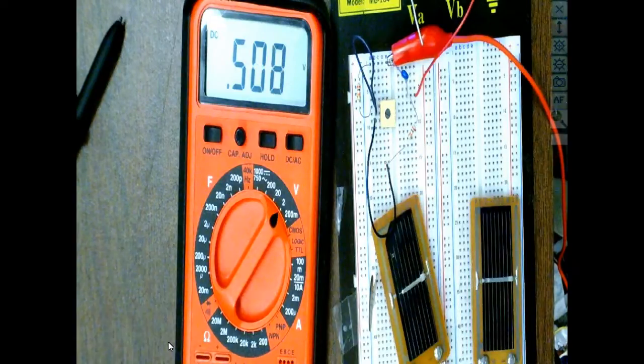The other type we have is what we call a proportional magnetic Hall effect, which is a little cheaper because this has the circuitry in there that latches. But these will actually give you a linear output, a voltage output that represents the strength of the magnetic field.